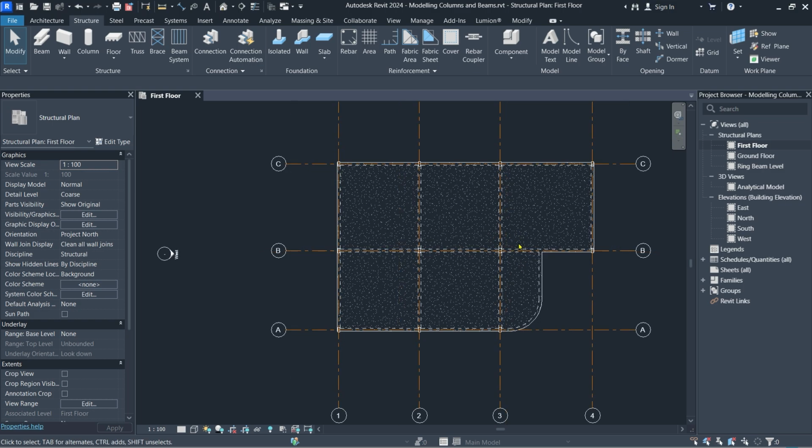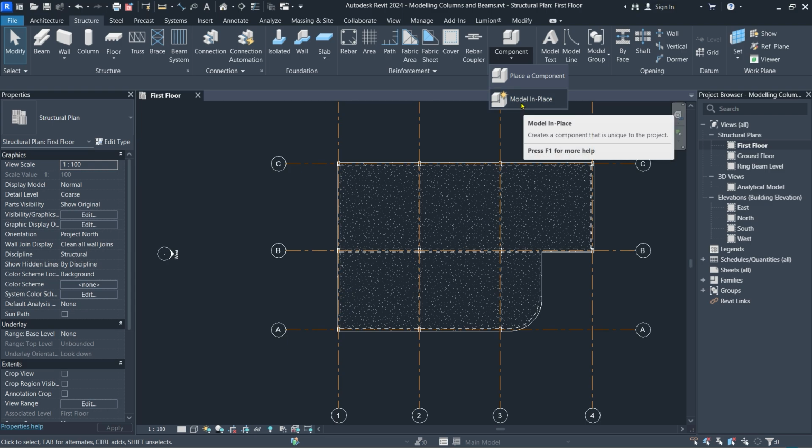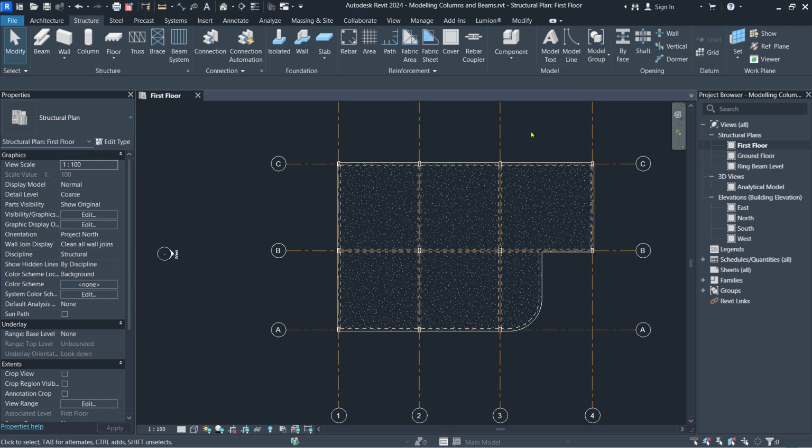There are so many ways you can, of course, come up with that. You can draw multiple slabs at that area. You can model the whole slab in model in place. You could model in place under this using this tool. I wouldn't want to bring it up right now, so we shall have a separate tutorial on flat slabs.